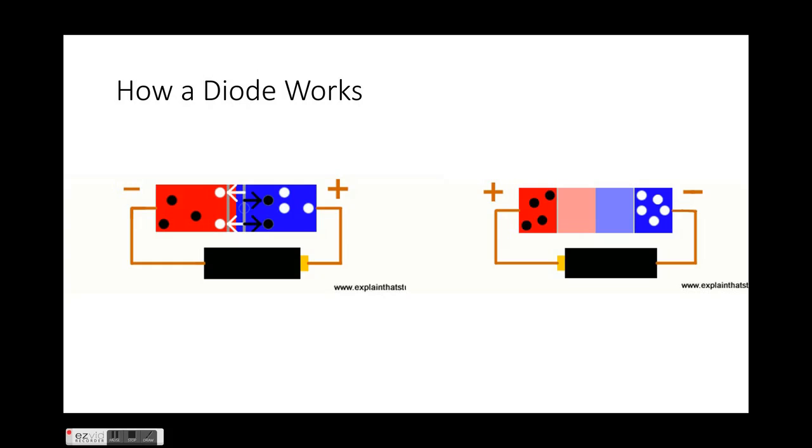When the positive side of the voltage source is pointed towards the N-type semiconductor, or the blue region in this case, the depletion region is going to shrink and result in less electric field. And vice versa, when the voltage source is oriented towards the P-type, or the red part for our purposes, the depletion region is going to increase, and we're going to have more electric field.